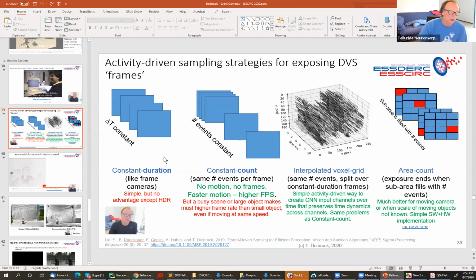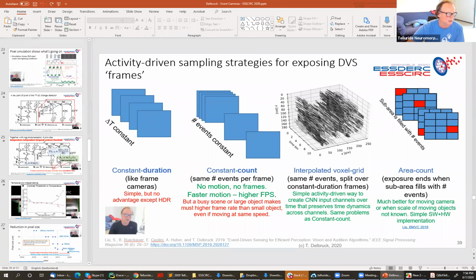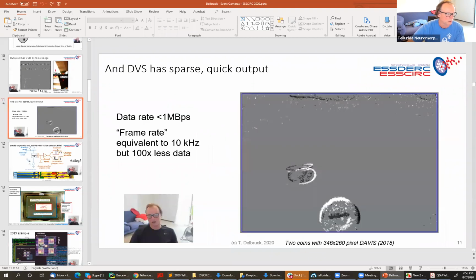And so, of course, when we started driving a neural network with DVS, we would collect frames of signed or unsigned DVS events, like you see in all these pictures that I showed in the very beginning of the tutorial. Basically, this is a histogram of some events over some time frame where gray means no events, white means there were on events, and black means there were off events. So say this is like a 1 millisecond frame. It means there were some off events here, on events here, and everywhere else there were no events. And so you consider this just a picture, kind of a granular picture that you can drive your CNN with.